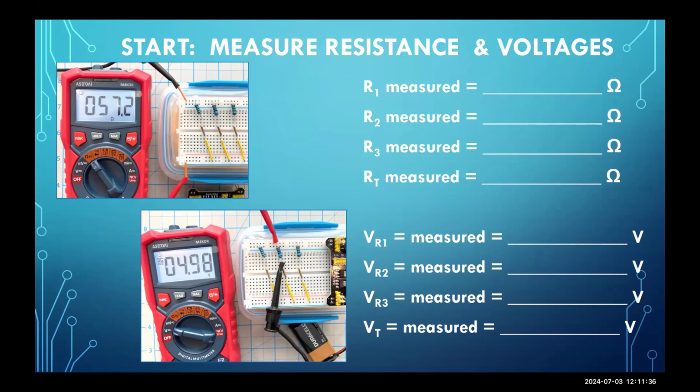I have some resistance within the board itself. I have some resistances of the wires. And so as long as we're pretty close to the calculated 56.9, and that's reasonably close, we're happy campers for these guys measuring our total in parallel. And now it's very important when you do this that the power supply is removed. The power supply cannot be on the board when you're measuring R total. If the power supply is left on the board, you will not be able to measure anything close to the desired resistance. So in order to measure total resistance, you have to remove the power supply.